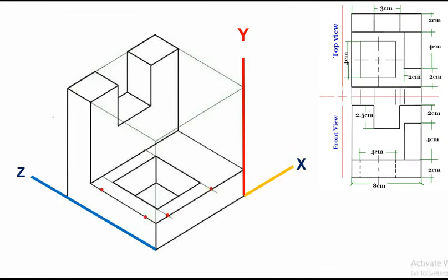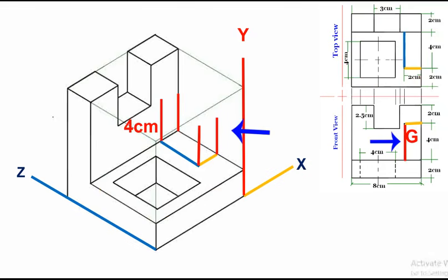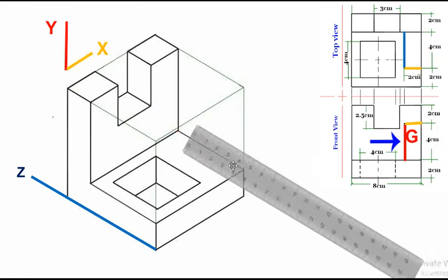Finally, create the last plane, which is a rectangle with dimensions of 2 centimeters by 4 centimeters in the top view. Extrude the plane to the desired height. Since we get the height dimension from the y-axis, refer to the front view. Connect the endpoints to complete the drawing. Move centimeters from point B to create it.